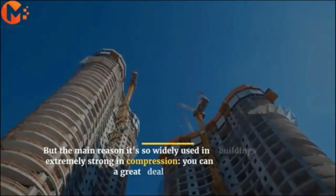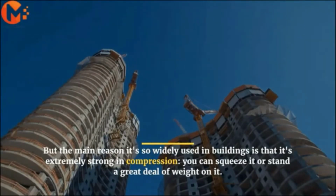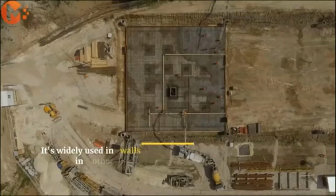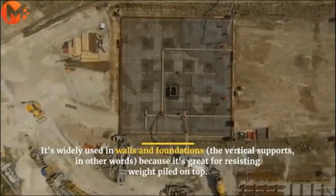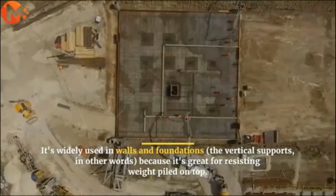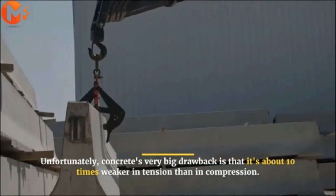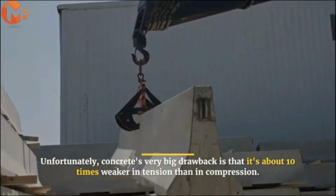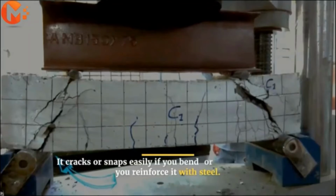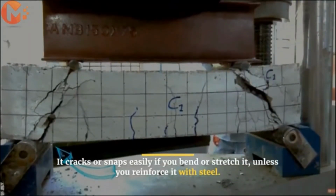But the main reason it's so widely used in buildings is that it's extremely strong in compression. You can squeeze it or stand a great deal of weight on it. It's widely used in walls and foundations, the vertical supports, in other words, because it's great in compression. Unfortunately, concrete's very big drawback is that it's about 10 times weaker in tension than in compression. It cracks or snaps easily if you bend or stretch it, unless you reinforce it with steel.